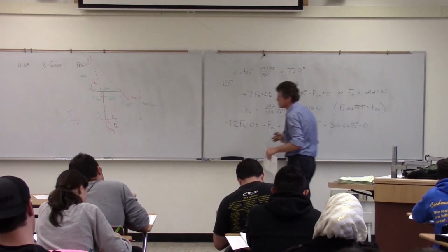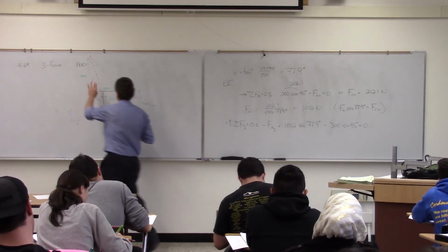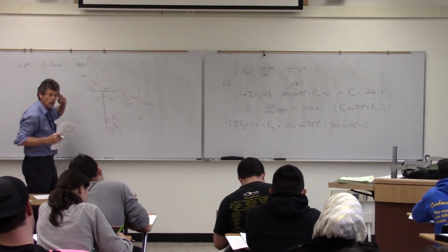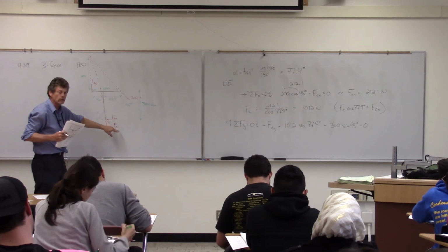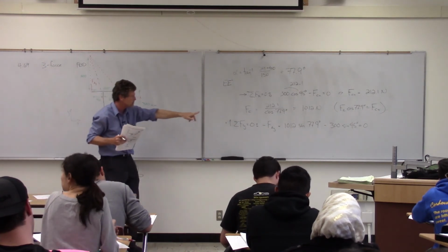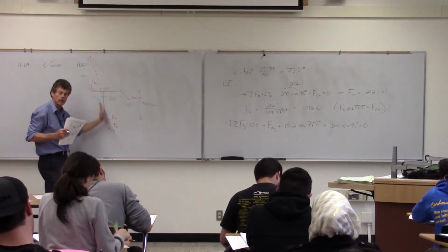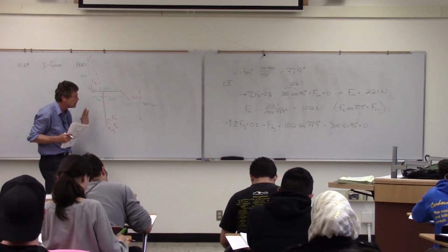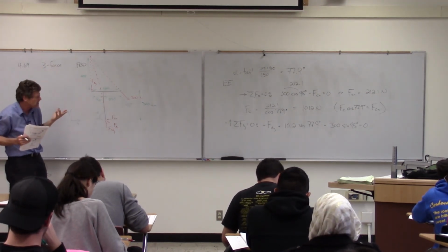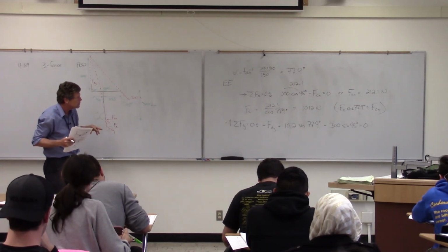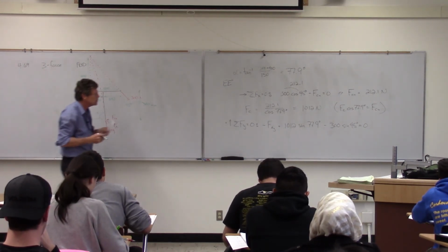And then summing forces in the y direction, I've got my unknown F_Ay there in a negative sense. I solve for F_C, so I'm going to take F_C times the sine of that 77 degrees, so I'm getting that vertical component. It's in a positive sense. And then my 300 again is going to be that same value of 212.1 newtons there.